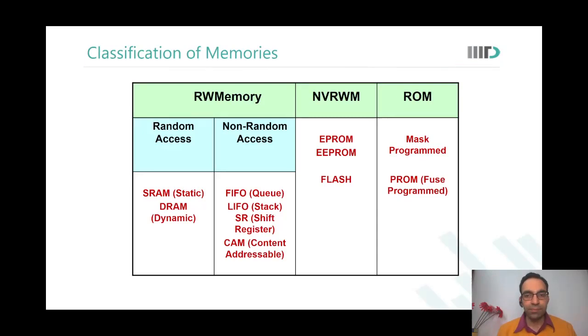So what exactly was the difference between the EEPROM and this PROM? I'm not able to get it. Okay, EEPROM is electrically programmable. You can apply a voltage of 12 volts to the chip and you can get it going. Fuse ROM may not be electrically programmable. With fuse ROM, you will actually have to physically blow away the fuse.